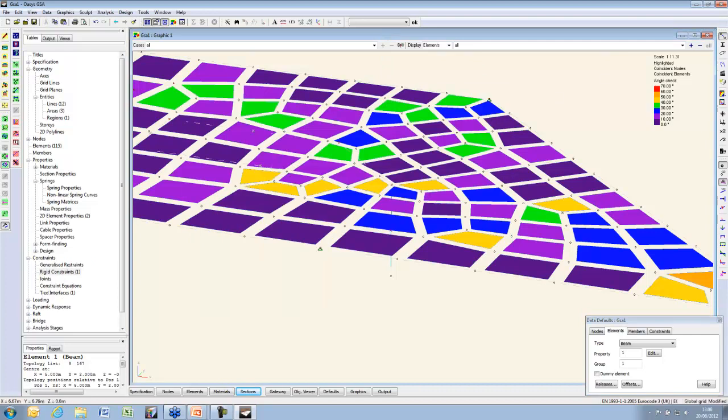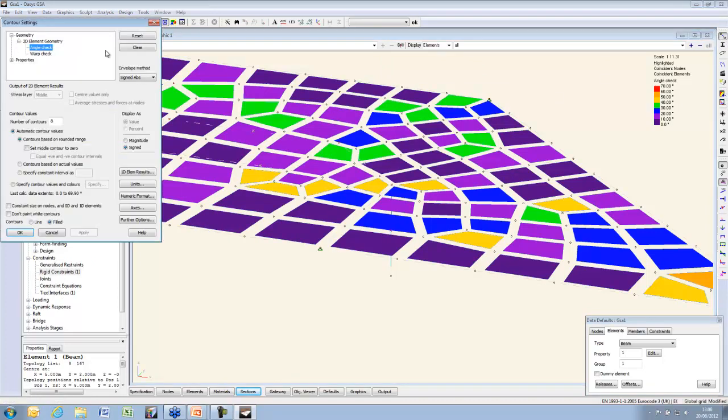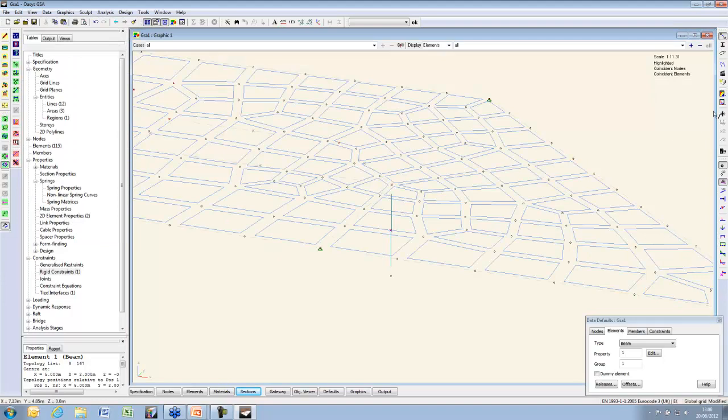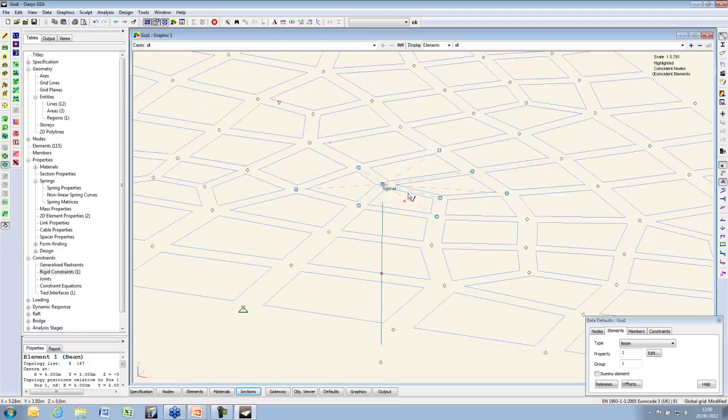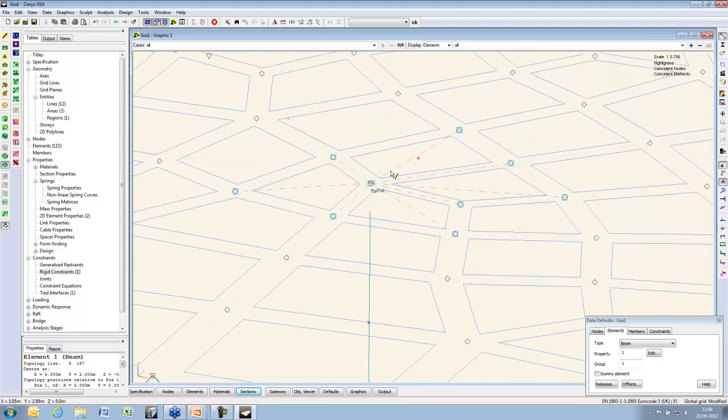We can see that this creates a rigid link from that column to the connecting elements, and so that will deal with those localized, unrealistic peak moments directly over the column, and give you better results.